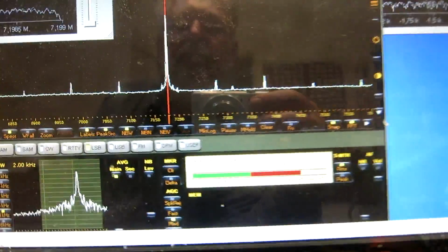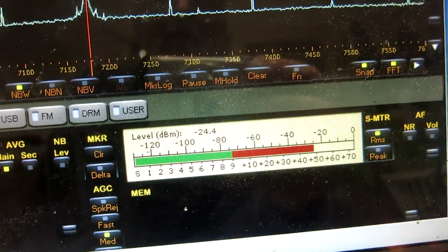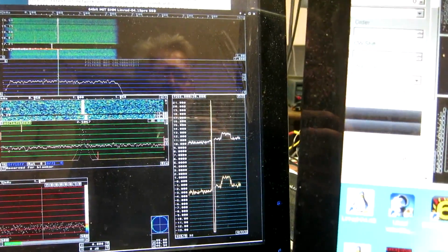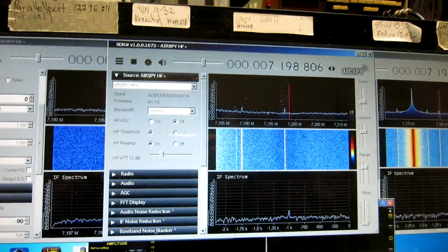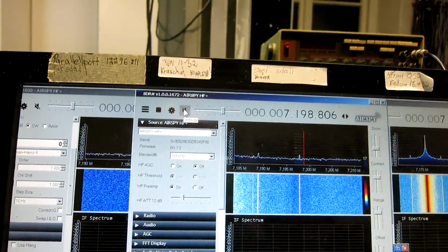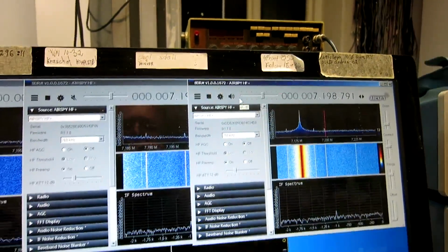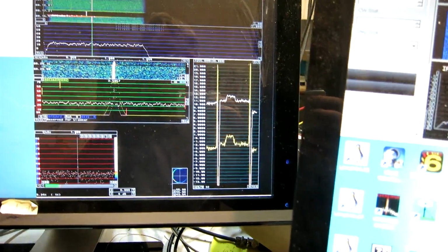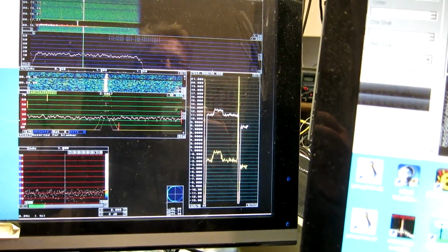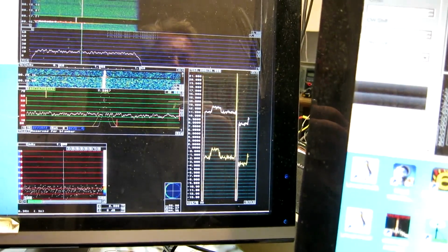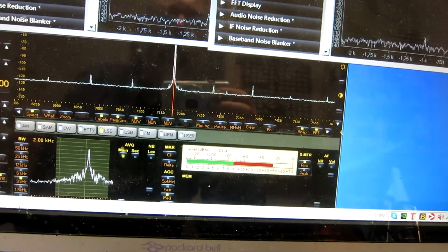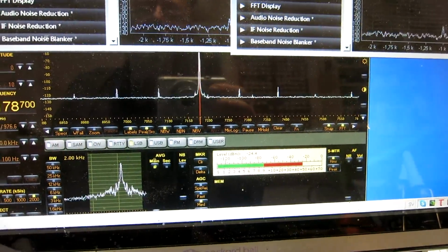Then I can look on the Perseus, and I find that the level is -24 dBm. Not very surprising. Without changing the level, I still have 3 dB degradation on this unit. And I switch that off, and I switch this one on. And then I remove the strong signal. And we still have about 3 dB. So they all are at -24 dBm at 20 kilohertz.